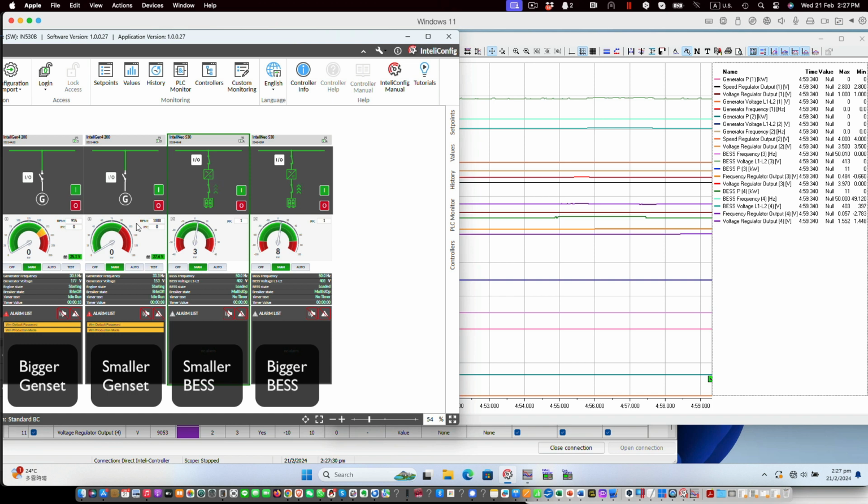So right now we're taking 11 kilowatts on a dummy load, on a test load bank. The two BESS systems are load sharing. I'm adding some more load. Right now the load is up to about 30 kilowatts. So the two BESS systems are discharging around 30 kilowatts evenly, based on their nominal power. They are taking their share of the load properly because the one on the right-hand side is larger.